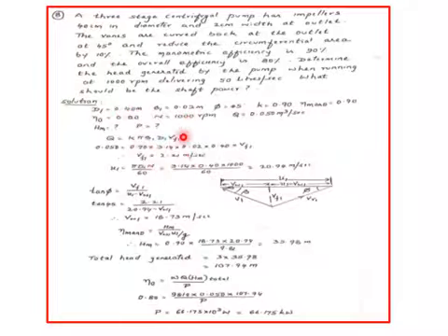Since D1 and N are given, you can find U1. Also phi is given, so you can make use of this triangle. Therefore tan 45 is Vf1 by U1 minus Vw1, which will enable you to calculate Vw1. Since Vw1 is known, the manometric head can be determined. Manometric head is manometric efficiency times Vw1 U1 by g, which gives us 35.98 meters. Since this is the head generated by one impeller and there are three stages, you multiply by 3. So the total head generated becomes 3 times 35.98, which is 107.94.